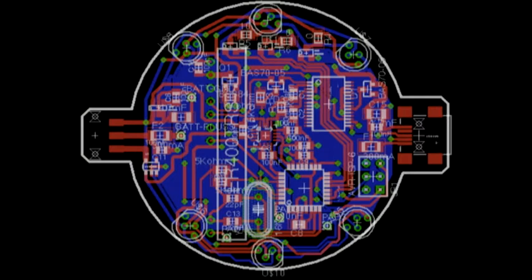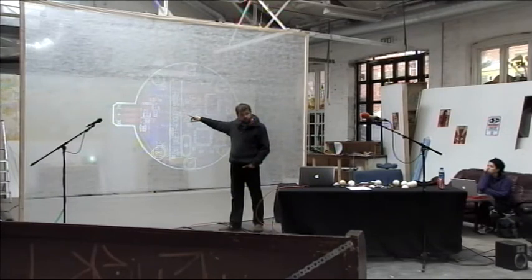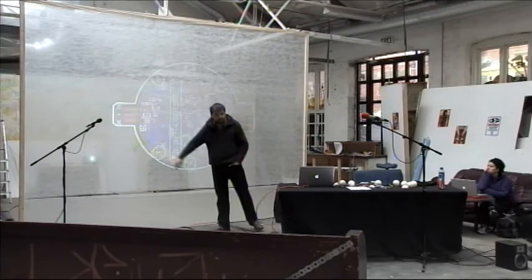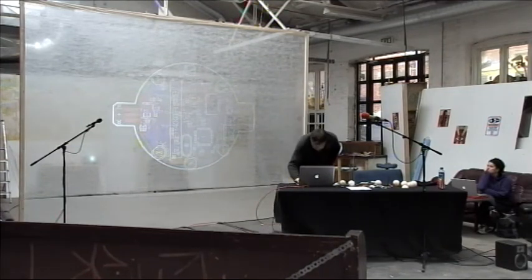Here we had the Arduino chip itself. This is the FDI chip that takes care of the communication on the USB port, so that we can program it. That's why we're using USB. There's an accelerometer, which will be straight in the middle of the board. And then there are some fuses that make sure that if something is shorted out, it doesn't blow up and all that kind of stuff. It protects the electronics around it.